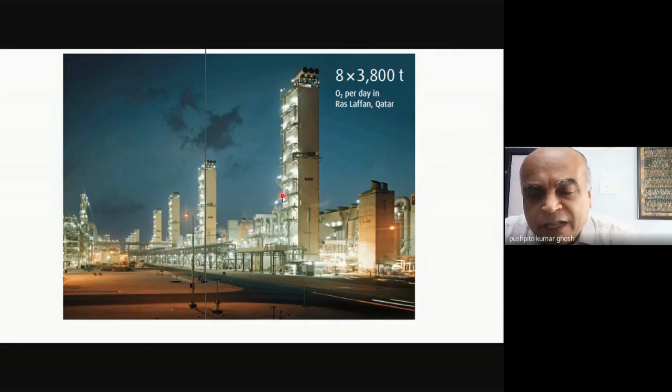What we discussed last time is the first approach that was taken by Linde, where the focus really was on recovering oxygen. It wasn't on nitrogen, but because the nitrogen is also getting liquefied, and finally, if you're going to discard the nitrogen as waste, then obviously the incoming air, the cooling of that will be done by this nitrogen largely, and also by the oxygen which you are recovering in a gaseous form, not in a liquid oxygen form.